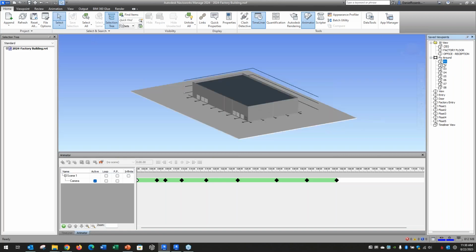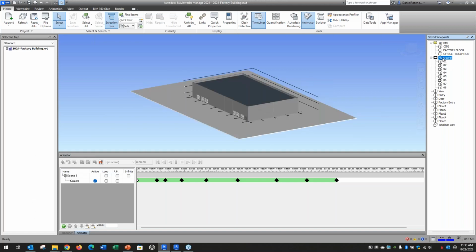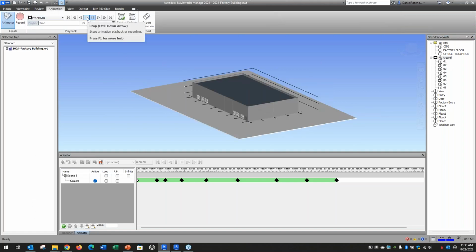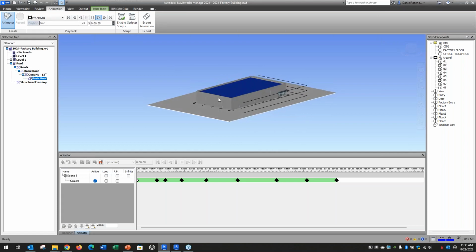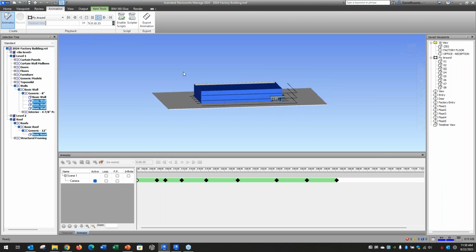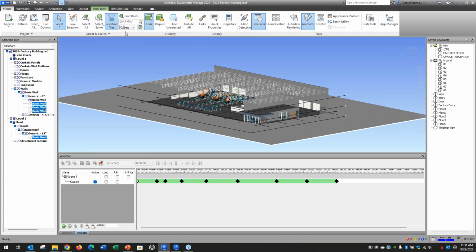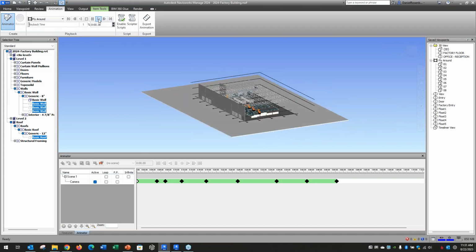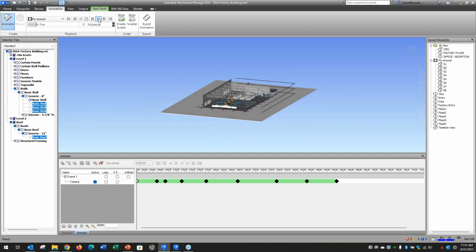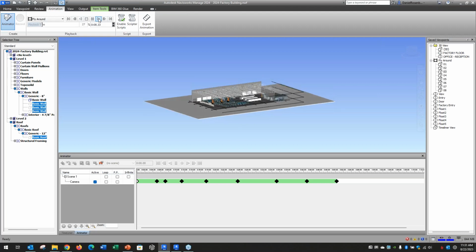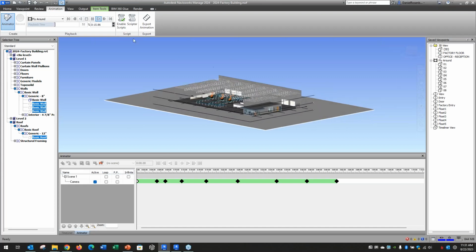The other thing you can do is with these saved viewpoints, you can easily have the software stitch them together. I just created very quickly some viewpoints here and told the software to seamlessly connect them together so I can kind of watch the building rotate around. Maybe I'll hide some of these so we can kind of see inside the model. So while it's spinning, but if I zoom, it stops the animation, but you can do a lot of different things like this, and you'll have the ability to kind of make it longer or shorter or swap views in and out.